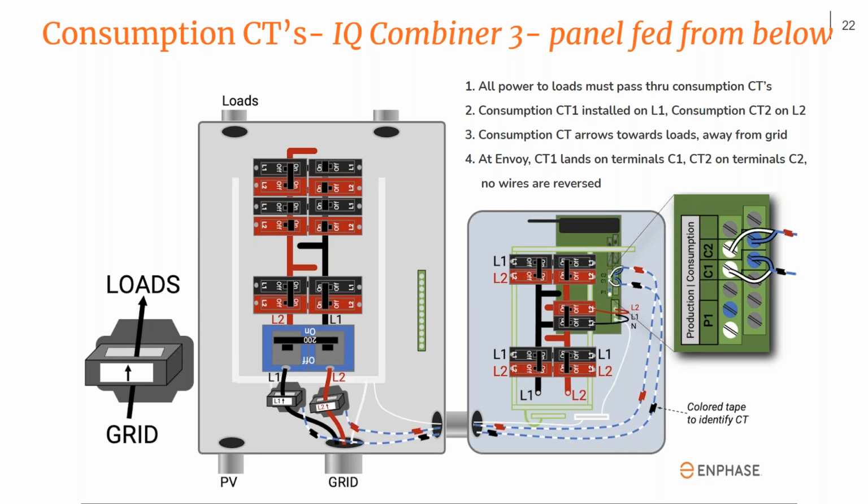Yeah, very helpful. And as we discussed, Danny, the consumption CTs are now included on the standard IQ combiners, whether you're dealing with the IQ combiner that comes packaged with the cell modem or not. Right. And as we discussed, the consumption monitoring is probably going to be the number one fallback point for any discussions with the homeowner on whether the system is actually doing what it's supposed to.